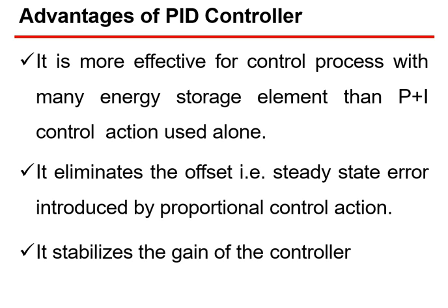Where there is any disadvantage related to the D controller, it is removed by the I controller, and where there is a disadvantage due to the I controller, that is reduced by the D controller. So they are complementing each other. That's why we are getting better options, and proportional is again there for its outstanding advantages that we have seen earlier.